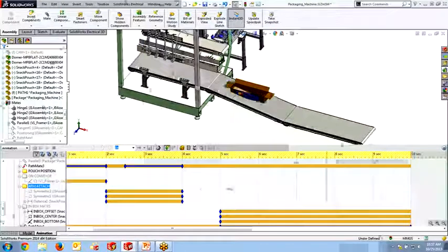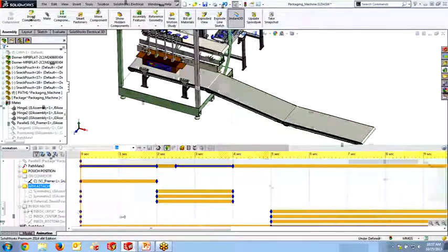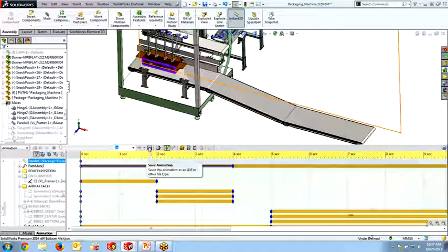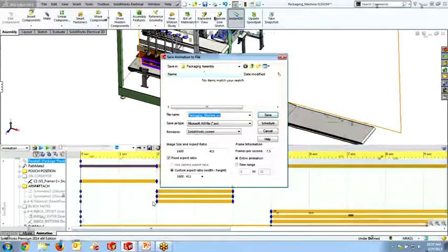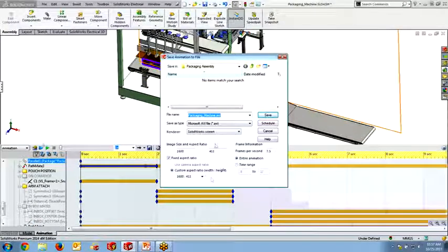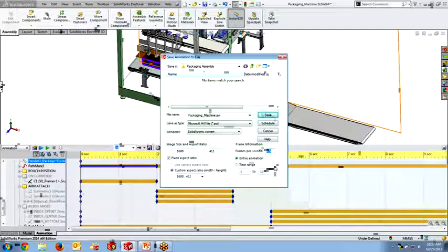Okay, so using this animator, you can create some really nice looking animations by selecting Save to save that animation out. Now, if you do click on Save, one thing that I'll point out is in addition to setting the resolution of the resultant animation, you'll also have things over here for frames per second. Now, just like movies and videos, I'd recommend a higher frames per second over the default of about 7.5, just because at 7.5 everything's a little bit jerky.